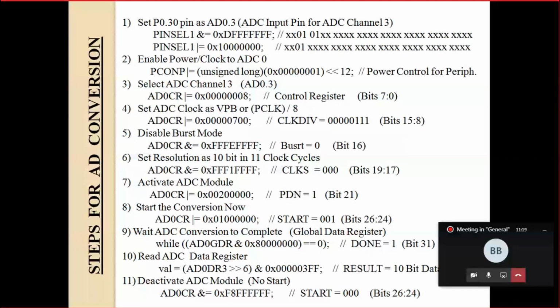So I am going to connect the variable point of the potentiometer to analog channel 3, and the corresponding 10-bit digital data I need to display on one port, say port 1 or port 0. Each 10-bit value will be displayed on 10 LEDs connected to one of the ports. I need to convert the analog voltage into digital data, and display that 10-bit value on 10 LEDs.